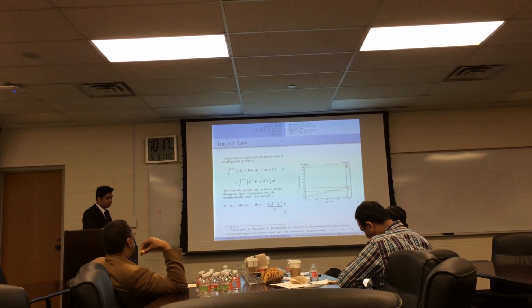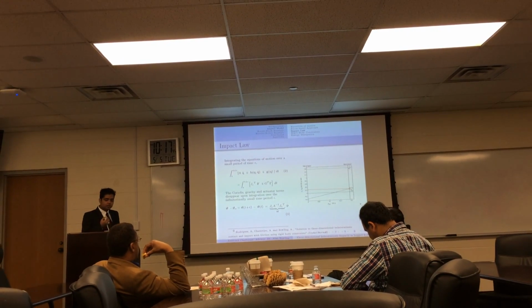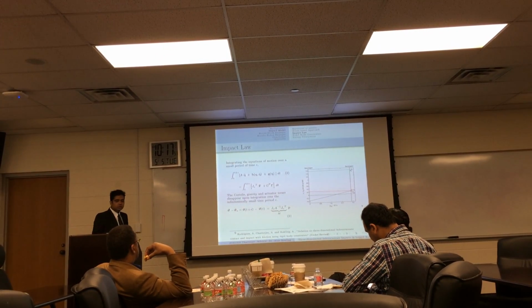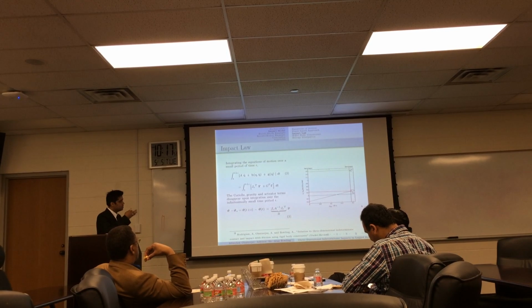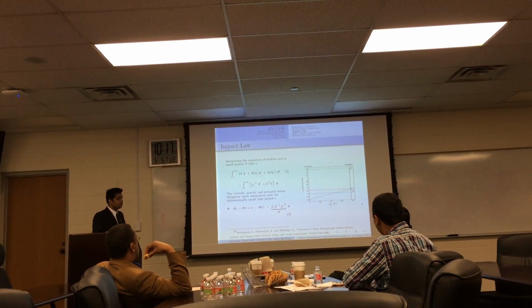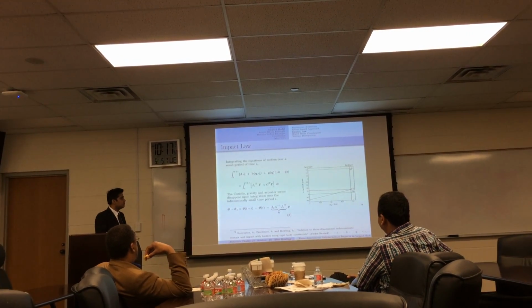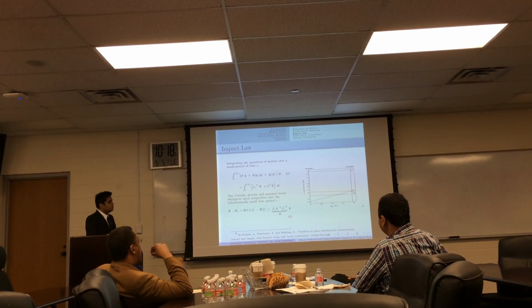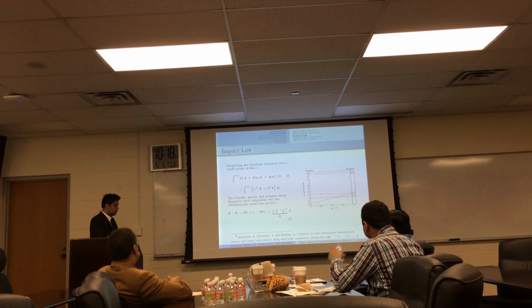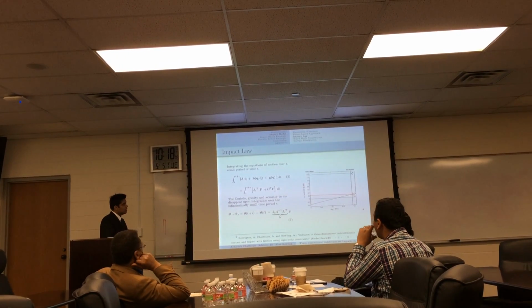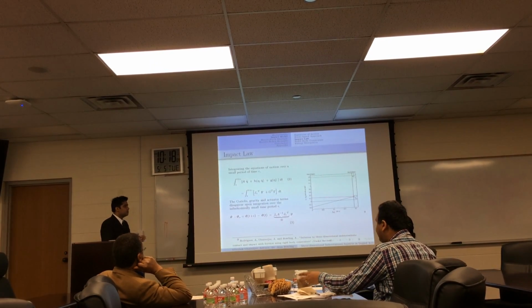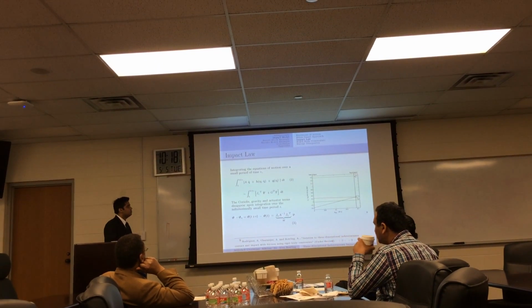Since this impact event occurs over such a small period of time, in the equations of motion the generalized accelerations and the constraint forces become very large during that time. To simulate that in a continuous fashion, we would have to reduce the time scale to be very small.